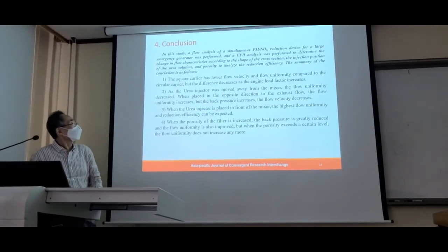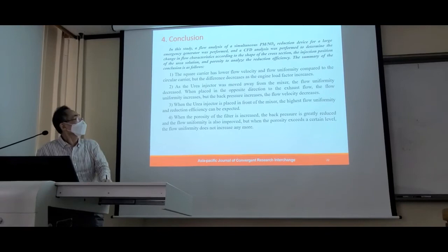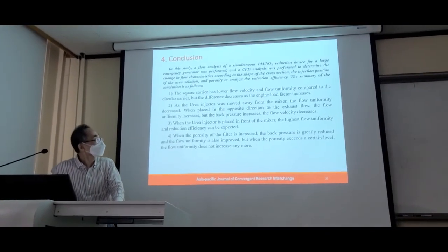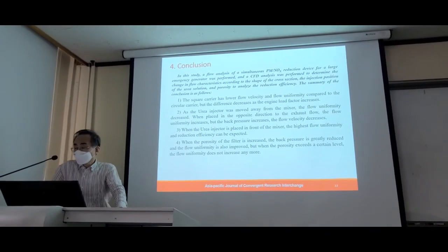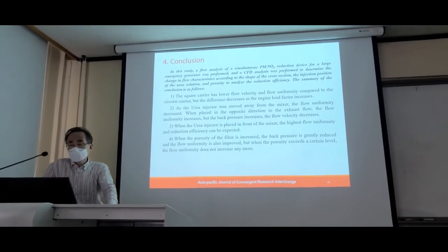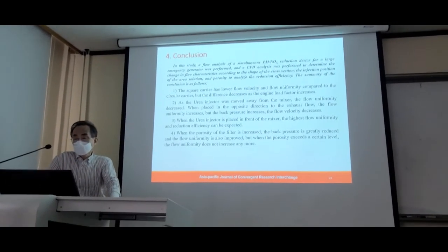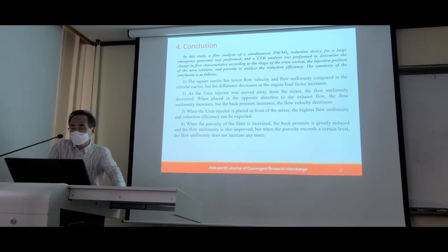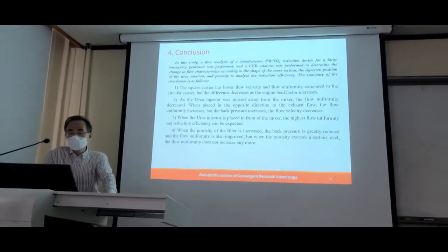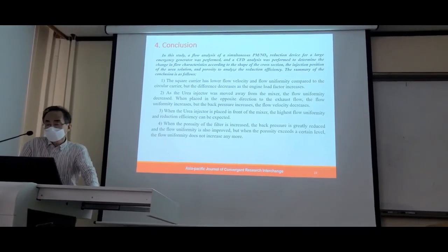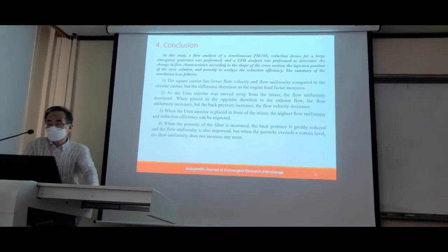Secondly, as the urea injector was moved away from the mixer, the flow uniformity decreased when placed in the opposite direction to the exhaust flow. The flow uniformity increased, but the back pressure increased. Finally, the flow velocity decreased.